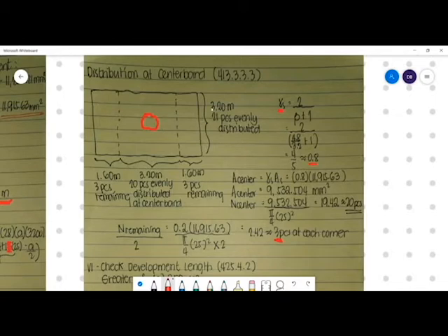So looking at this, we have at the longer direction, at this dimension, 21 pieces of evenly distributed bars. But on the short direction, we have 3 on the corner, 1, 2, 3. And we have 3 also here. But on the center, we have 21 pieces evenly distributed.